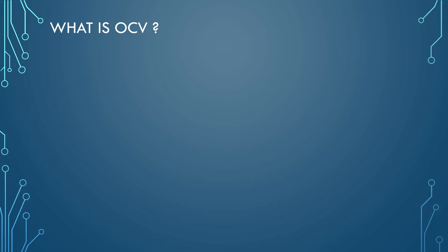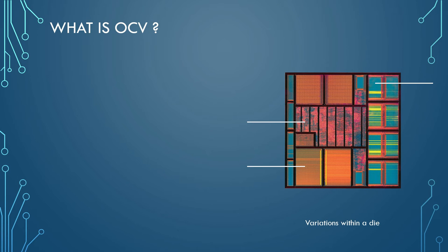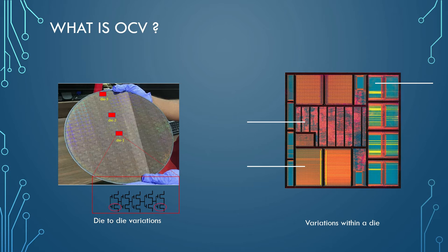Alright, let's get started. After a chip is manufactured, process and environmental parameters may not be uniform across different portions of the die. Due to process variations, identical MOS transistors in different portions of the die may not have similar characteristics. These differences are due to process variations within the die. In this section, we will analyze the process variations across one die. These are called local variations, which are much smaller than the variations across multiple manufacturing lots and different dies. That is called global process variations.